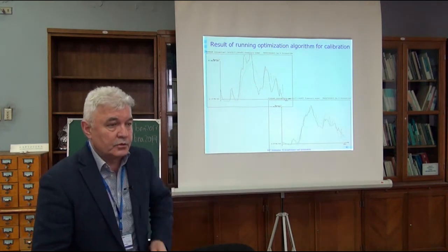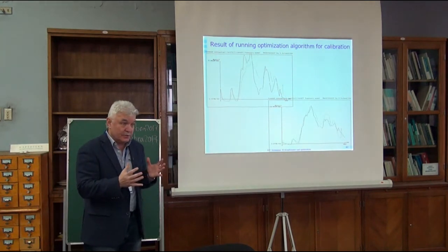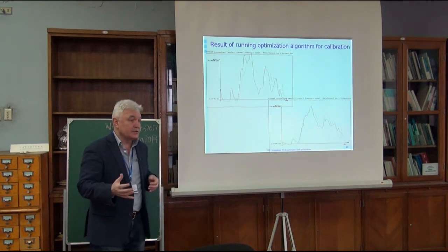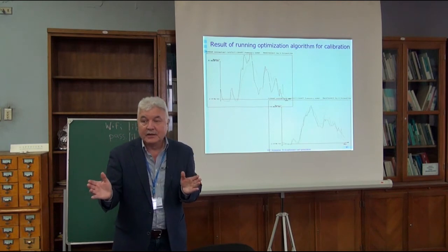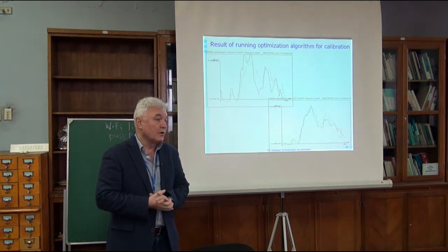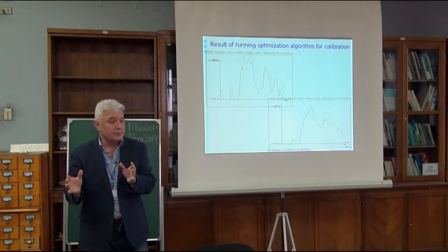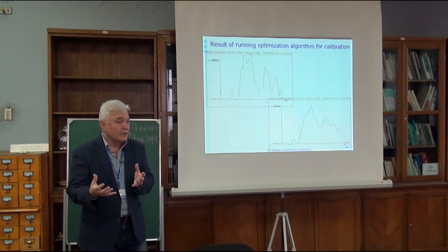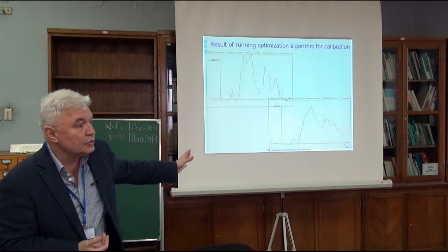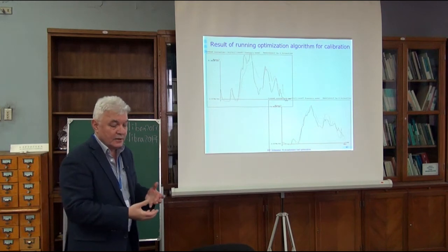Now, where the hydrological knowledge comes in, it comes in the experience, because these are lumped parameters. You understand, they cannot be measured. So you have to have some experience with these models. Otherwise, you would be doing strange things. You may find completely physically unrealistic parameters, which would still strangely give you a small error, but it's wrong. Even if error is small and parameter values are physical, you should not use them if they do not have physical interpretation. So again, first is hydrological knowledge, or simply knowledge, and second is tools that help you, in fact, to run models in a structured way many hundreds of times.